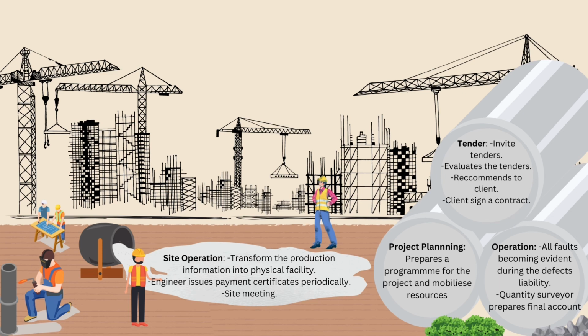Meeting. On completion of the building, the client or architect applies for a temporary occupation license, which, if required, is granted by the Building Control Authority after it has inspected the building and tested the equipment and installations. An application for a final certificate of completion may be required after more stringent tests at a later date.